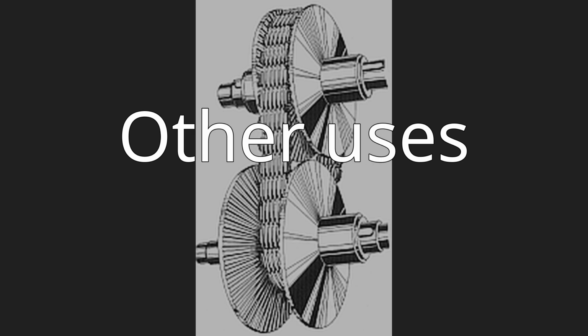Other uses. Some drill presses and milling machines contain a simple belt drive CVT system to control the speed of the chuck, including the Jet models J-5816 and J-5818. In this system, the effective diameter of only the output shaft pulleys is continuously variable. The input pulley connected to the motor is usually fixed in diameter or sometimes with discrete steps to allow a selection of speed ranges. The operator adjusts the speed. Winches and hoists are also an application of CVT, especially for those adapting the transmission ratio to the resistant torque.